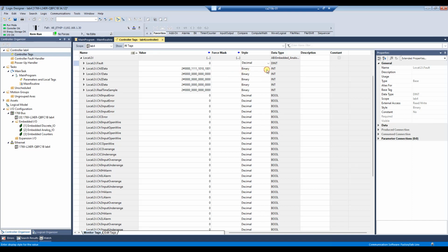Okay, and I hit the wrong one there, but I can do it to this one. And what you notice here now is it's reading back 4009, representing 4009 millivolts or 4 volts. And you'll notice it's not exactly 4 volts, it's 4.009, but that's a very small error. Okay, no need to worry about that.